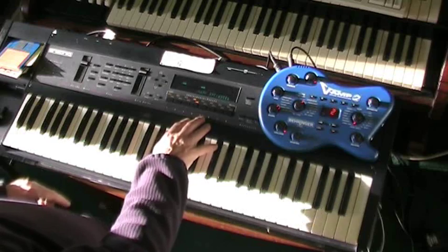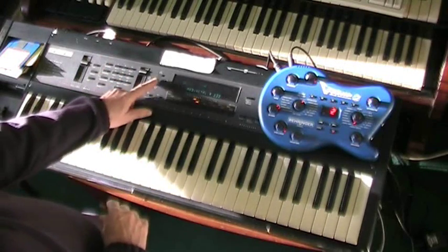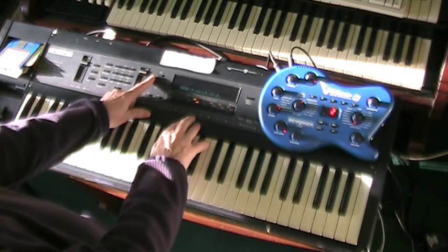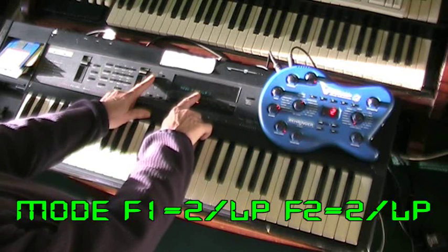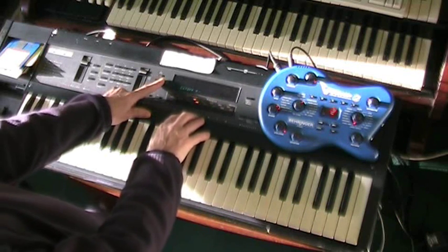The first application I'd like to show you is to use it as the filter control. In this particular example, I realise you can't see this display, so let me read through some of the displays. I've set the filter mode to filter 1 is low pass, filter 2 is low pass. That gives me a 4-pole low pass filter.